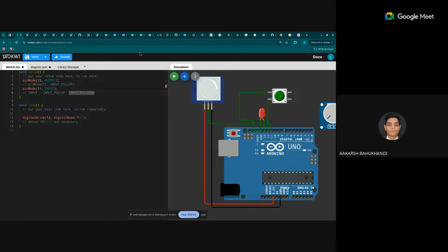Okay. So a quick example of that, maybe controlling an LED. Let's take another LED. We'll make it a green LED. This is our green LED. I'm going to connect it to pin 10, and this to ground. So this green LED is connected to pin 10, right? In Arduino, things are simple. You just have analog read, analog write, and everything works. So you can easily start coding with this.